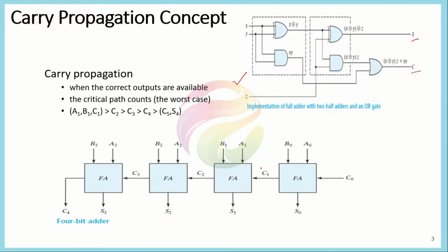If you consider how long it would take to give the accurate result, then we have to understand the carry concept, or the carry propagation concept, in this whole system. We generally consider the worst case scenario. Worst case scenario means that the carry is generated in all the columns, and for all the next columns you have to consider the carry bit too.